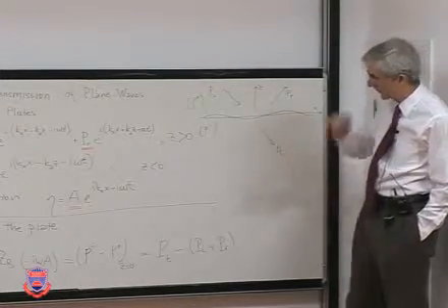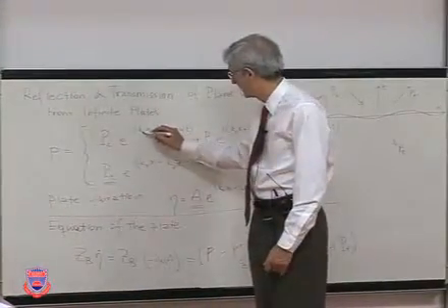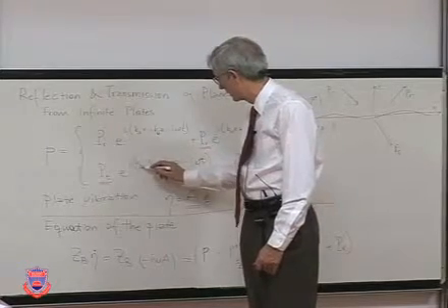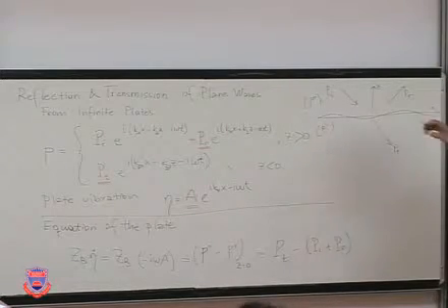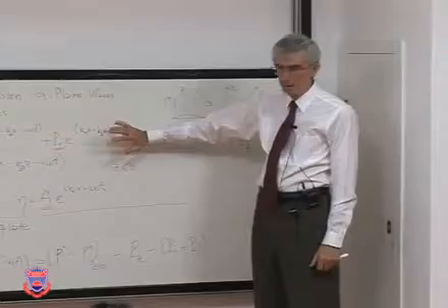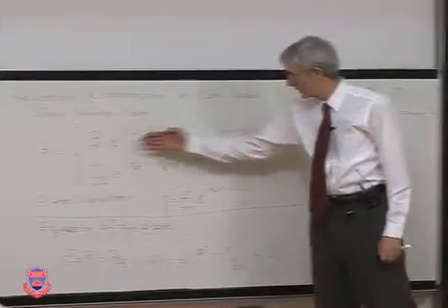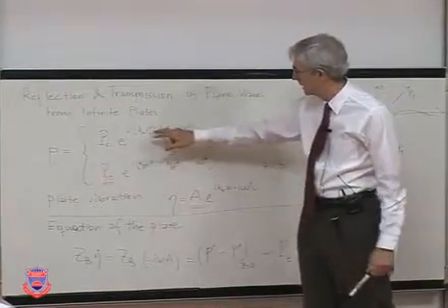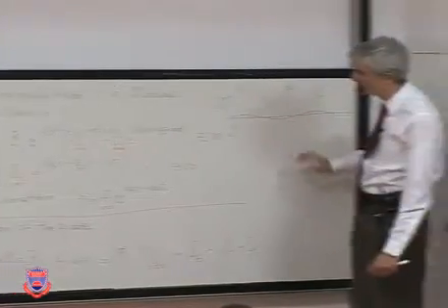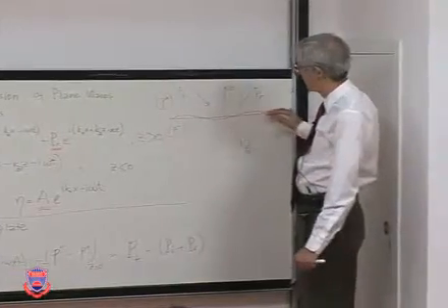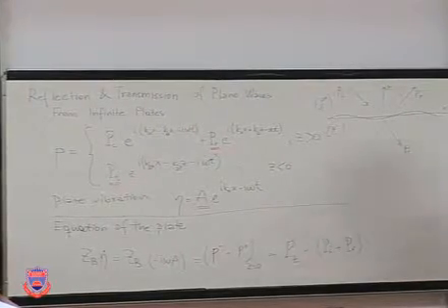the other side. So to be more correct, and you don't have to worry about these, but these would be one in the most general form, two different media. But the important thing to do here is, number one, to write the pressure expressions for incident, reflected, and the key here is to get the directions right, to get the components right, and then a transmitted sound to the other side, and then the equation or expression for the plate displacement itself.